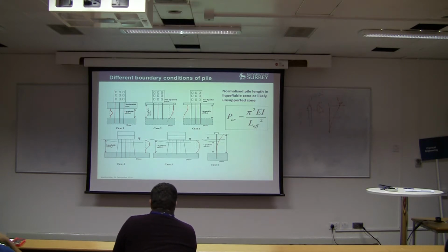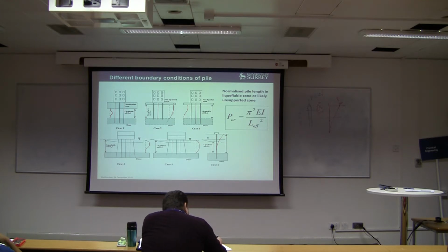If it is embedded 5 diameters below, that's fixed. And if it's partial, in between the two, do you use your judgment? When it's not a full 5 diameters, a hand calculation won't give you the number. They try to model it more mathematically to see.